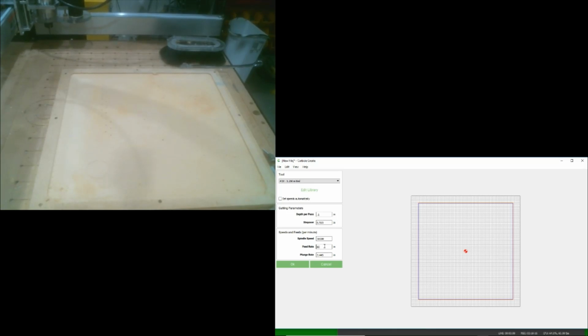If it bothers you that much, you can drop it down and be more conservative to, say, 40 or 50 inches per minute. I don't recommend dropping it any lower than that, particularly when you have such a high RPM. Otherwise, it throws your feeds and speeds all off. Plunge rate, 30 inches. Again, that may seem fast, but we're only talking MDF.